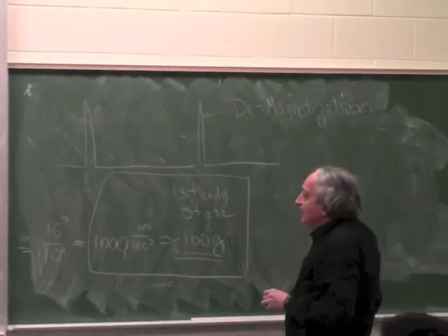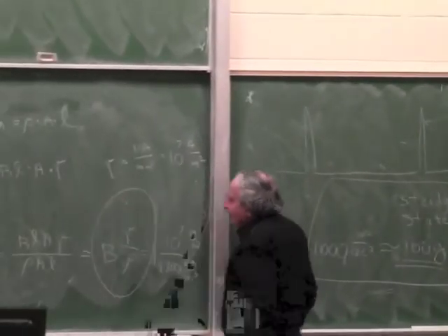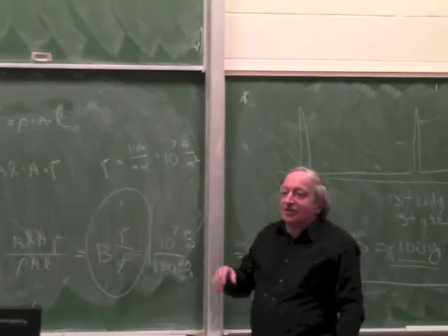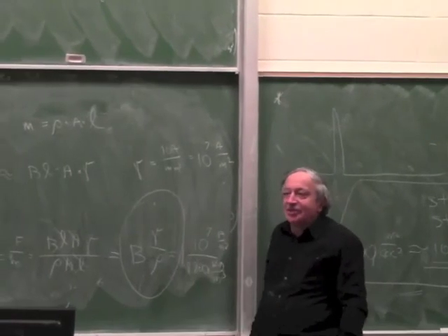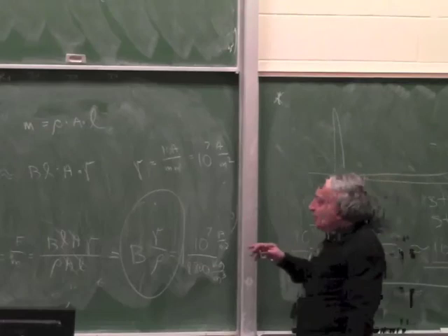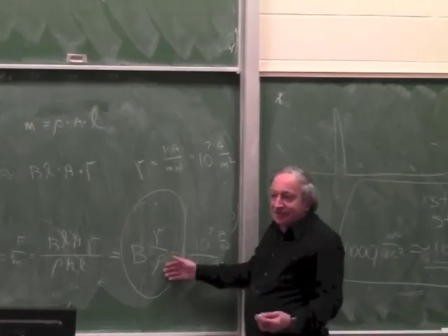Okay? So now when we look at this formula, now we can start thinking maybe there is another degree of freedom. Instead of using copper, maybe we should use other materials. So what we're looking is a material which has the best ratio of current density to weight, to density.